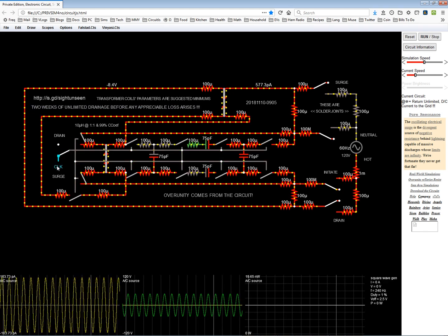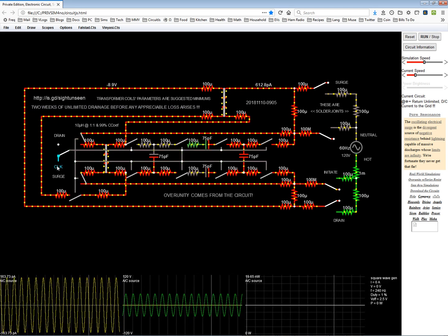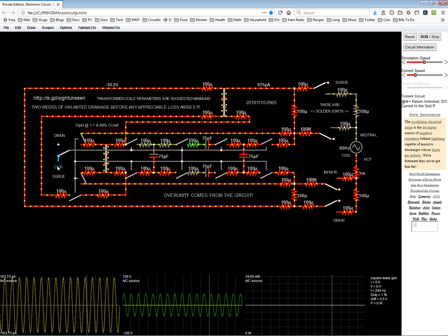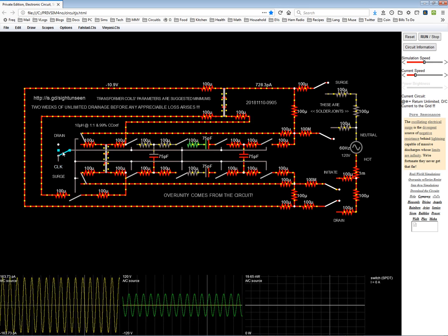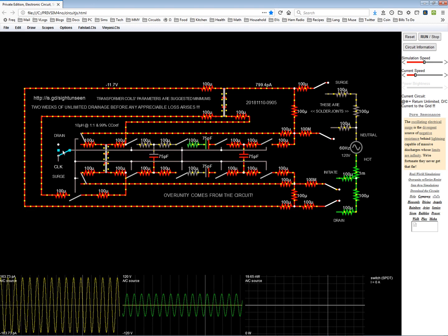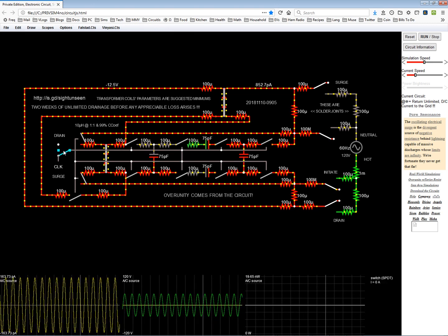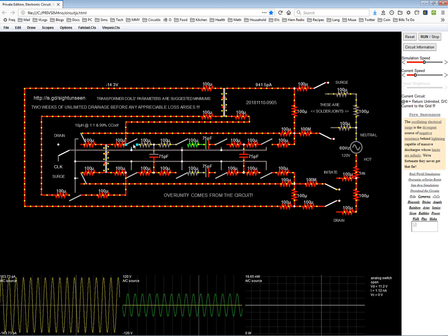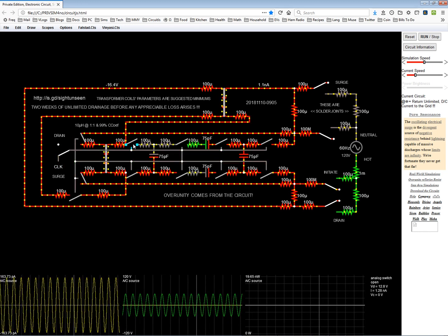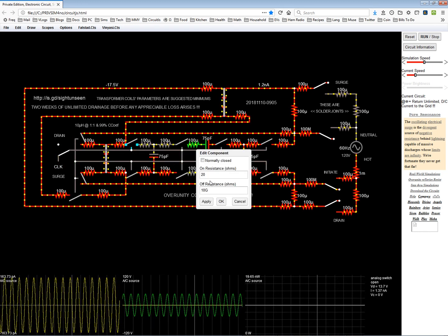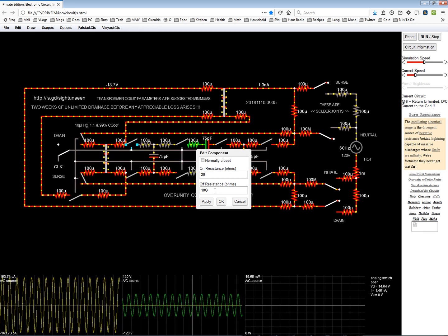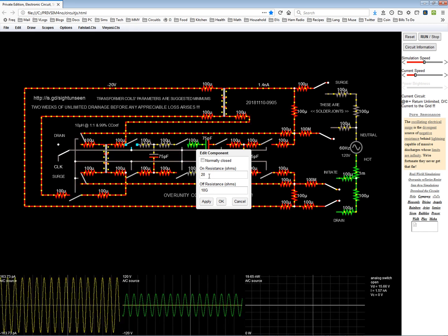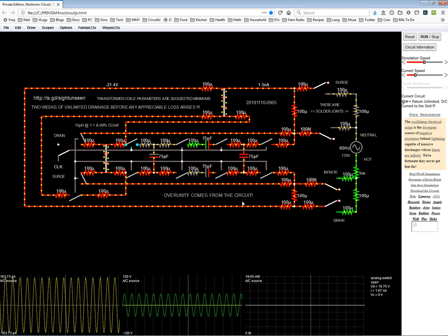Now, I only have a clock timer when we surge, to regulate the surge and prevent us from surging too quickly. And then when I'm done with the regulated surge, I flip over to drainage mode and disconnect the clock. So then all these switches have to remain open all the time. And each of these switches, when they're open, they have 10 gigaohms of resistance. And when they're closed, they have 20 ohms of resistance.